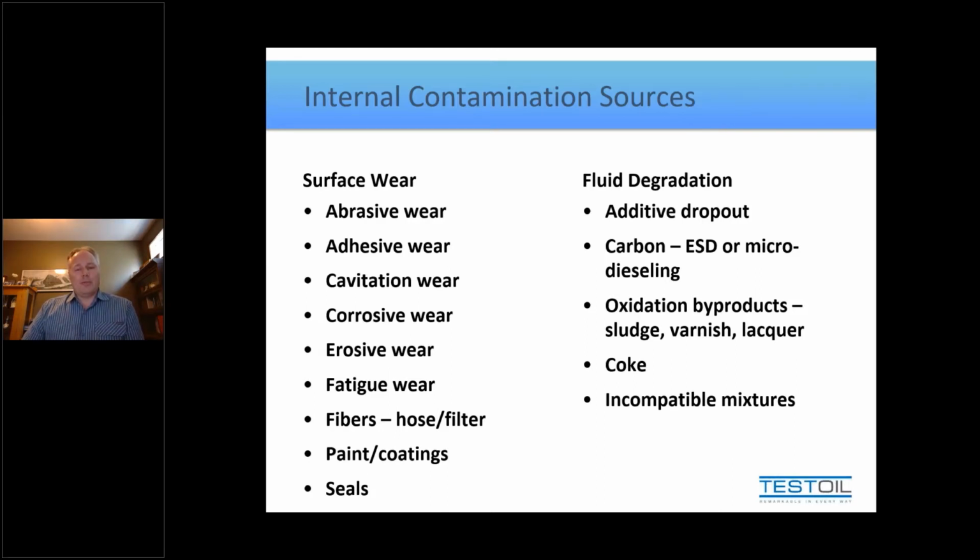The other form of internally generated particulate, though, is the less obvious one, the one that has nothing to do with machine wear and has more to do with lubricant degradation. So sometimes we see particulate formed as a fallout from how the lubricant is degrading or otherwise reacting. And that can come from a variety of mechanisms, but oxidation being the primary one that's most common in most systems and will occur over time, regardless of best efforts. So when particles are created through oxidation, they can occur a few different ways.